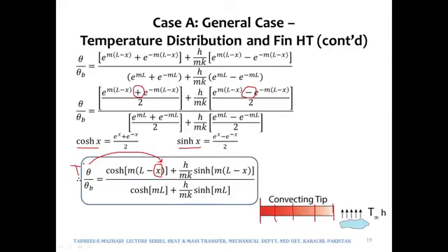It was logarithmic in the case of cylindrical coordinate system, and for the spherical one, I had derived two for you, and I had then asked you to derive the third one on the same lines, which was 1 over 4 pi k times 1 over Ri minus 1 over R naught. It was in fact the thermal resistance. And the temperature distribution in case of fins is in fact hyperbolic.